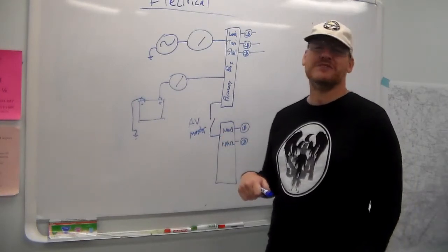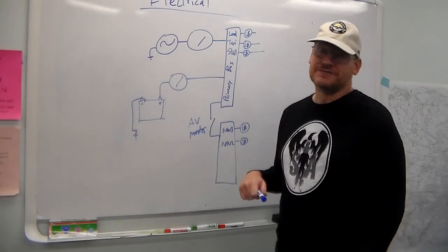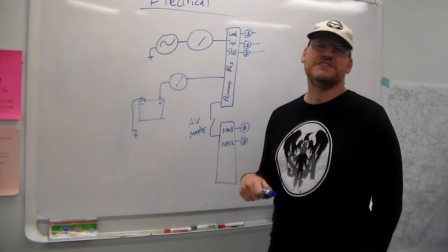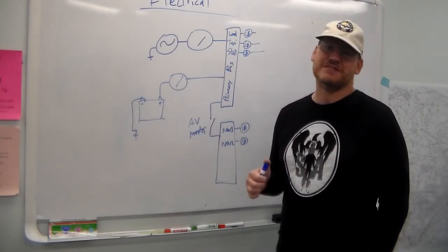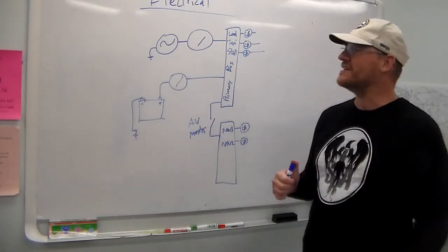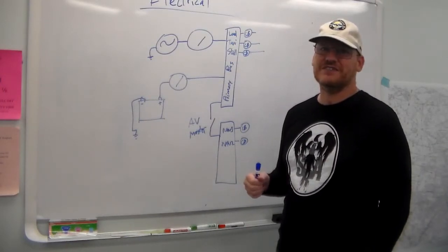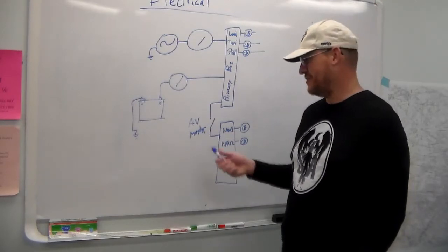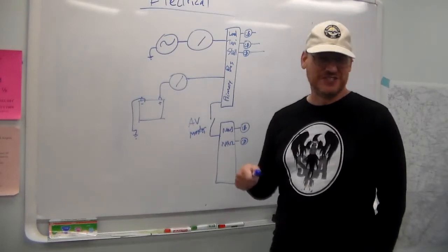You might say, why would you want to do that? Well, you can get a spike in voltage, and you have these nice modern avionics that can get messed up. So there's nothing worse than having your nice modern avionics and all of a sudden you're buying more modern avionics because, oops, I left the stuff on while I was cranking the engine or shutting it down.